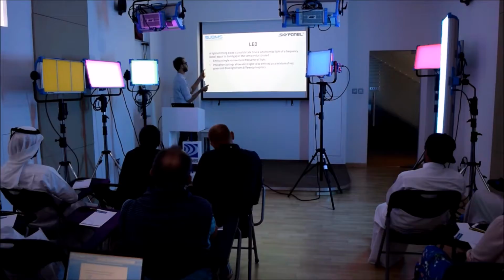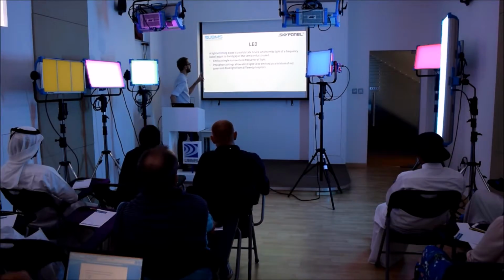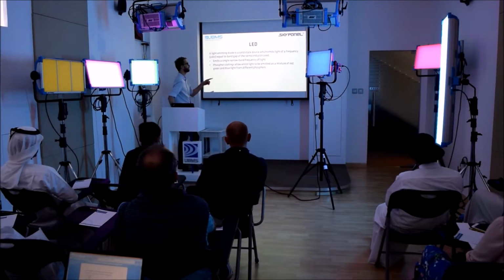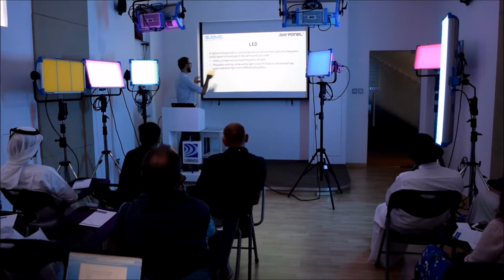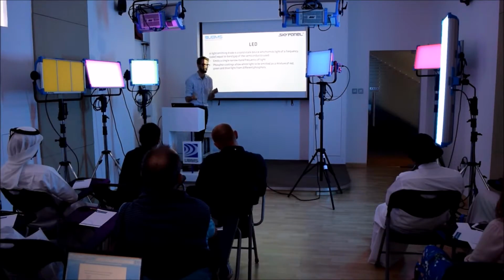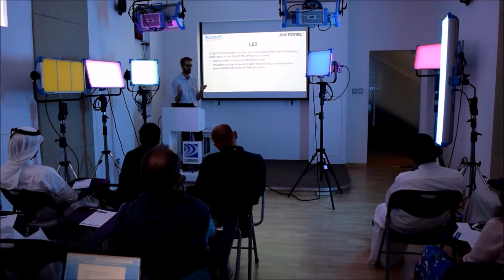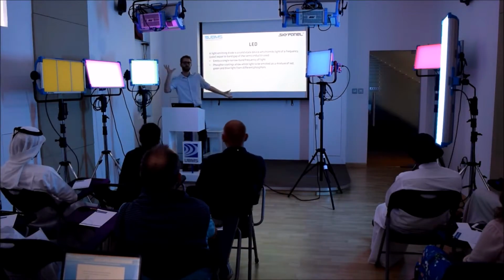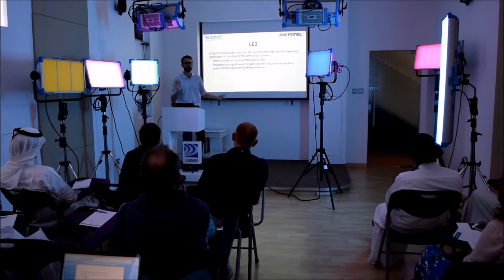The better way is using phosphor coatings, and that's what we do now. Phosphor coatings allow white light to be emitted as a full spectrum mixture of red, green, and blue by using different phosphors. Phosphor is a coating which takes a certain frequency of light, absorbs it, and emits all kinds of other frequencies of light. Basically, that's what a phosphor does.